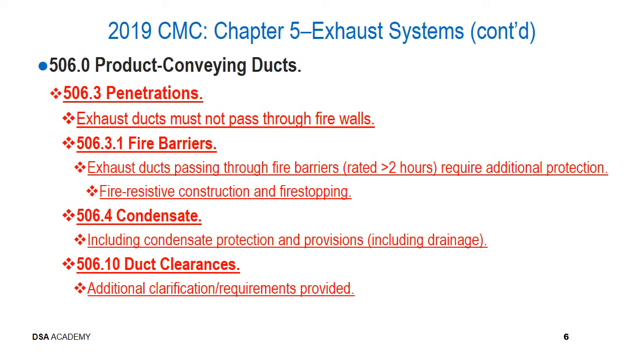Ducts in these areas that may have condensate, which has a potential to collect inside, must include condensate protection and additional provisions, which we're not going to talk about in detail, but may include drainage.